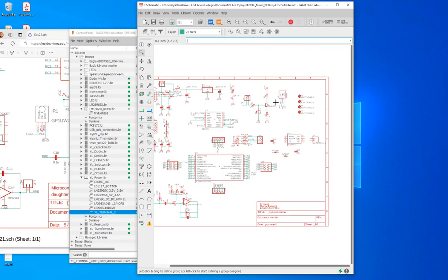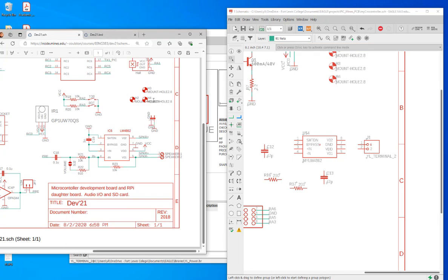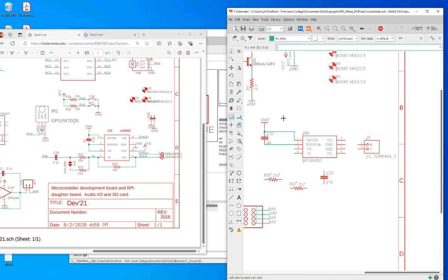So now I will just look at the schematic here and make the connections. So first, we also need a ground. Ground is getting rotated and placed here. And capacitor value, this is 1 micro, 1 U. And this one is in the middle. New value, 1 U, right? 1 U. That's what I did. And this should be grounded on the top. And you want to stretch this a little bit because you need a connection. So this one is getting all the AC signals decoupled by this capacitor. Okay, and plus in is also shorted to here.